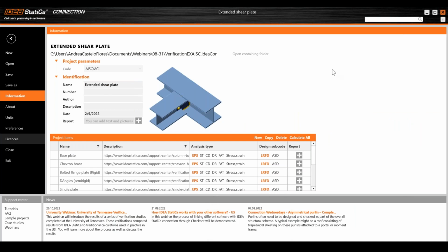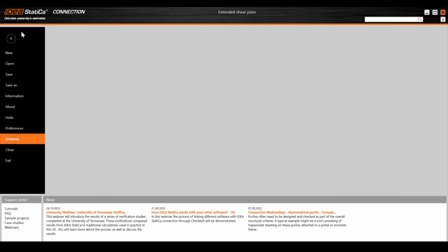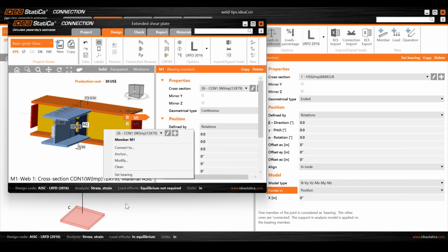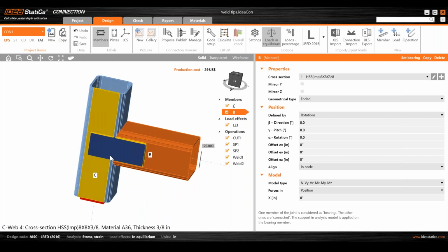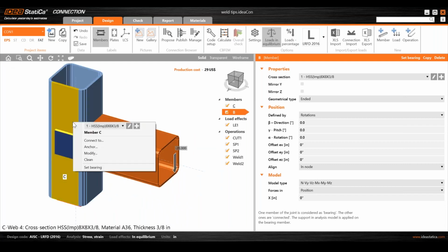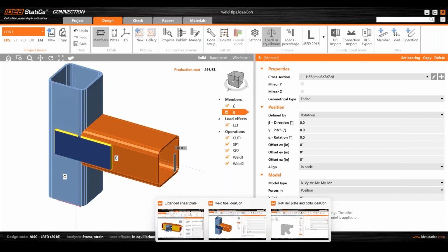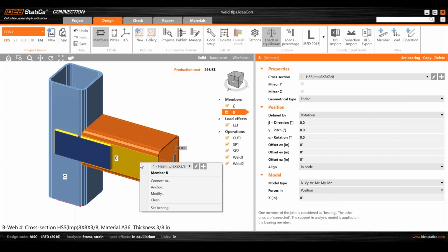Sorry. So what Andrea is trying to showcase is basically when you are looking at, for example, that shear plate connection, you can right click and you will have a button there saying create section, if I'm not mistaken. And this would give you a 2D drawing of your welds and bolts that you could then use to print out. So a small detail of your connection perpendicular to the element that you clicked on.